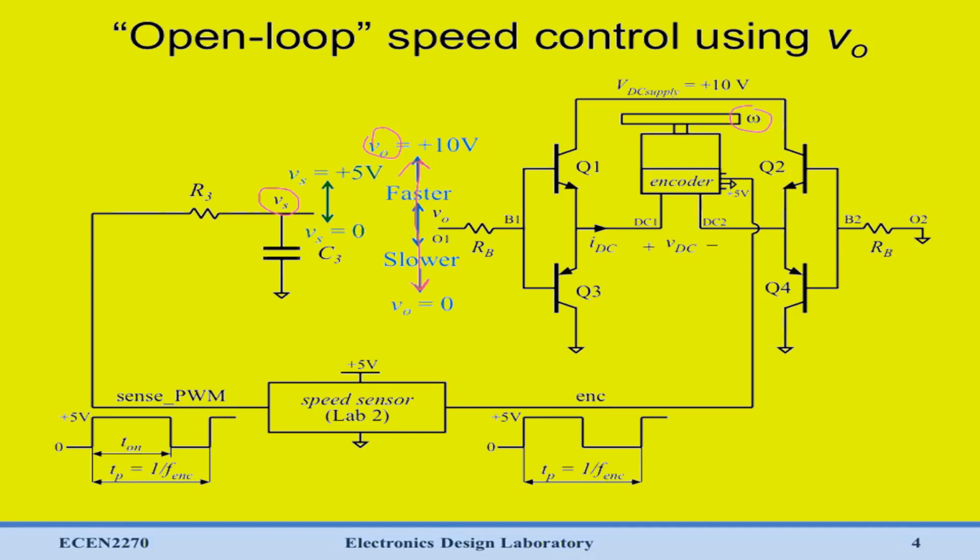If we have different torques on our motor, for example if our robot's going up a hill or down a ramp or something, it can take more or less current in order to achieve the same omega. Meaning that if we simply measure Vs once, determine the correct VO, and then try and use that at all conditions to get some motor speed, it's not going to work. In this system we'll have to continually be measuring Vs and modifying VO in order to maintain a constant omega.